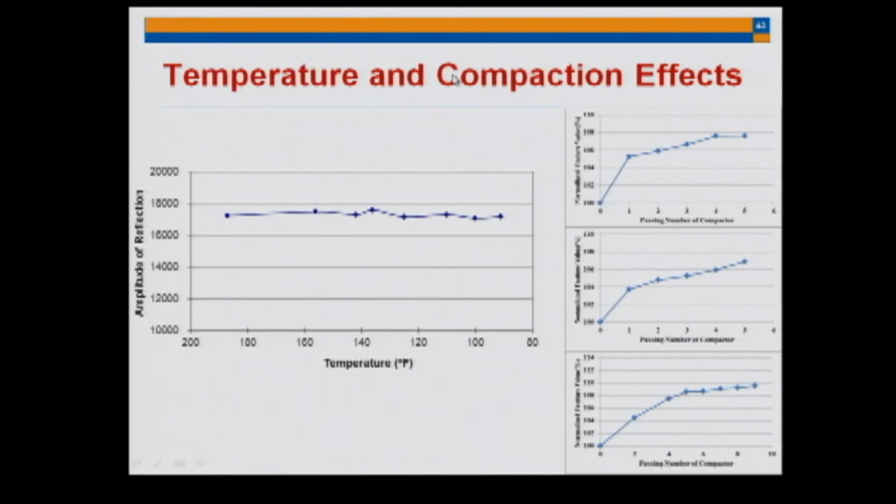As you can see here, the temperature has no effect whatsoever. We know that, but we just want to prove it to people who may question this. As we compact, you can see that the amplitude here is increasing, which means the dielectric constant is increasing with each pass.